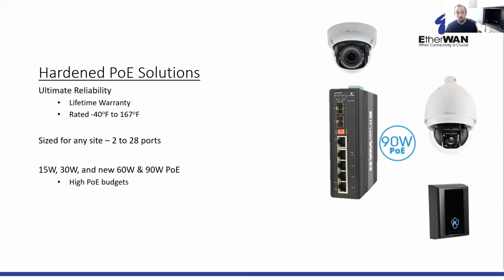That could be your access control components, of course. A lot of folks have single door or multi-door PoE powered access control, and having 90 watt, I think you'll see more of that now with multi-door controllers having enough power to run their draw. You're going to see expansion beyond just security devices on this. A huge new market that this opens up is PoE lighting. If you poke around the internet, a lot of your lighting providers are already having placeholders on their websites for this category of devices.